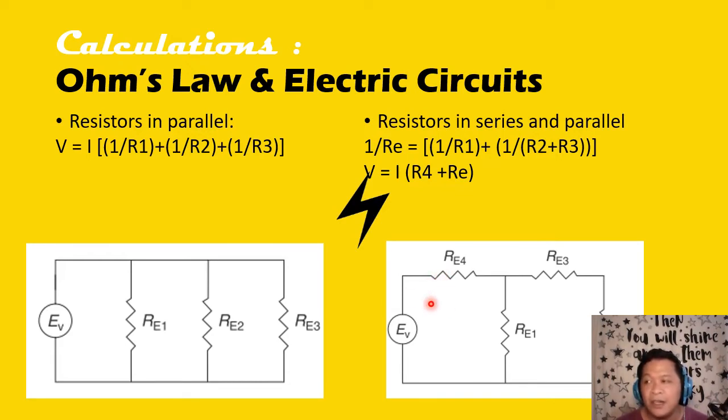So in this case, we could see that resistor 4 is in series with the circuit, and then parang yung resistor 2 and 3 saka resistor 1 naka-parallel sila, but resistor 2 and 3 is in series with each other, so collapse them here, and then we take the reciprocal of the sum of resistors 2 and 3 and the reciprocal of resistor 1 since they are parallel, and then we now treat this as the circuit being parallel to resistor 4 and the collapsed circuit, which is resistors 1, 2, and 3.